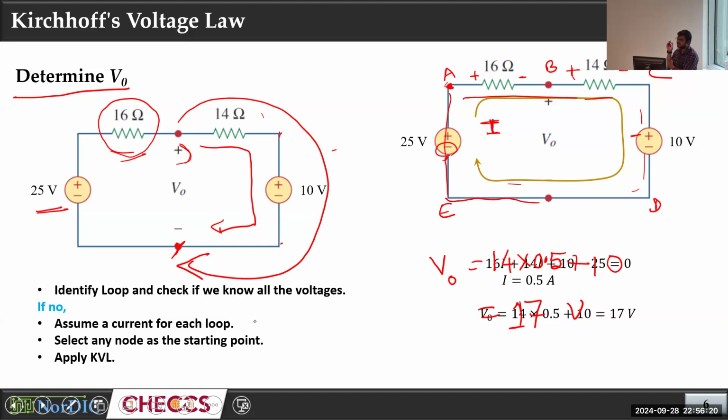Yes, that's a good question actually. If I only considered the right portion, you can also consider the left portion. That's also the same thing, right? Same calculation. But there I considered the right path because that's easier, because that's in the same direction as the current, but here it's in the opposite direction. So here we will have to assume a negative current. Yes, check it yourself. It should have the same value.